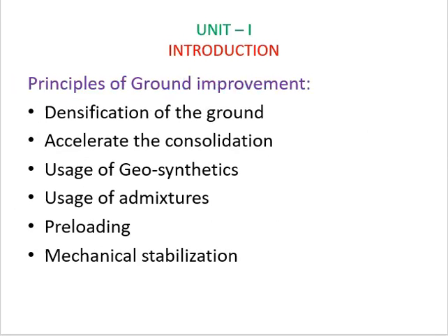Then principles of ground improvement. In that, first one is densification of the ground. For cohesionless soils like gravel and sand, strength will be increased by compaction itself. Hence, densification of the ground plays a major role in the ground improvement of granular soils.